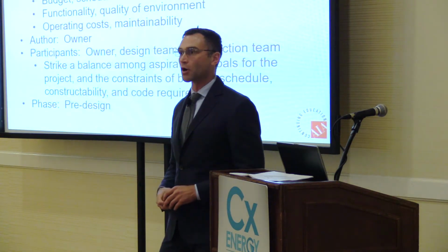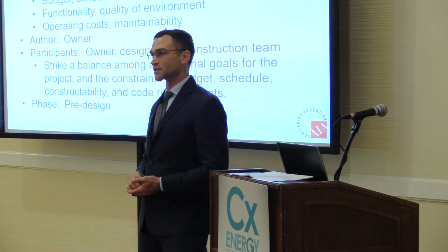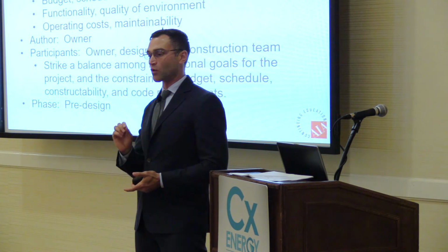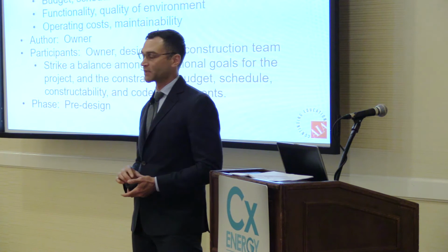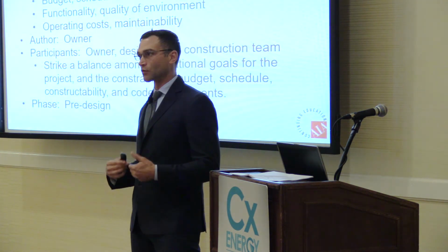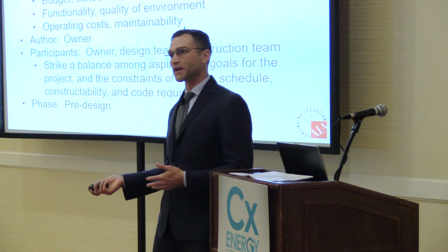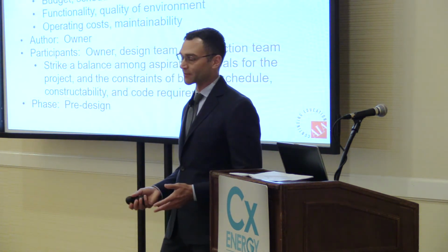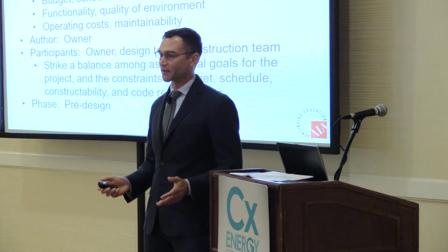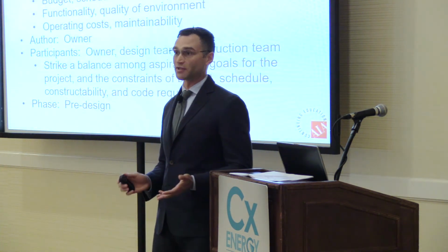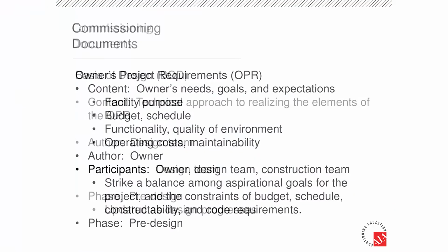How does the OPR apply to lighting controls? Just like we said, the questions we ask early help us with functional testing at the end. If you can, ask the owner, what do you want this schedule to be? What is the purpose of this space? Where do you want occupancy sensors, time delays? Ask that question early. Often you may not get the answer, but you can at least document that you've been asking. And that is an important part of what we do.